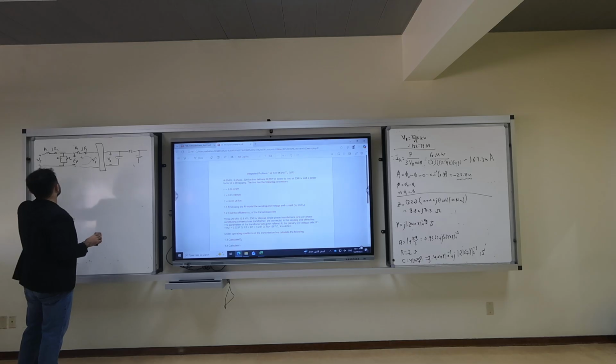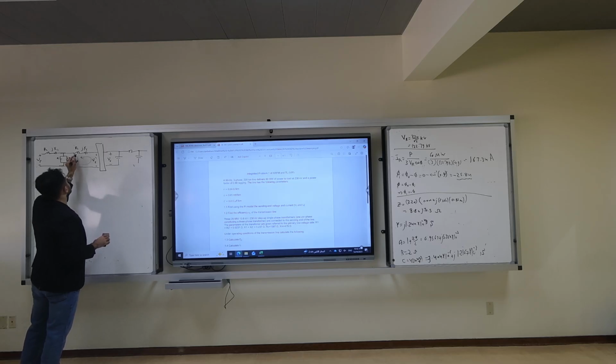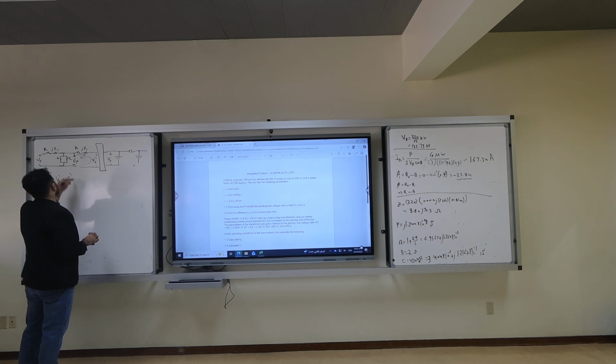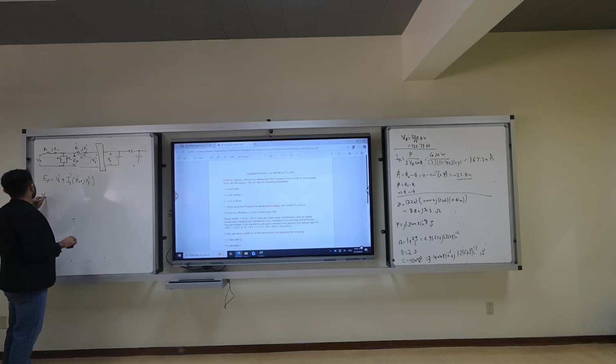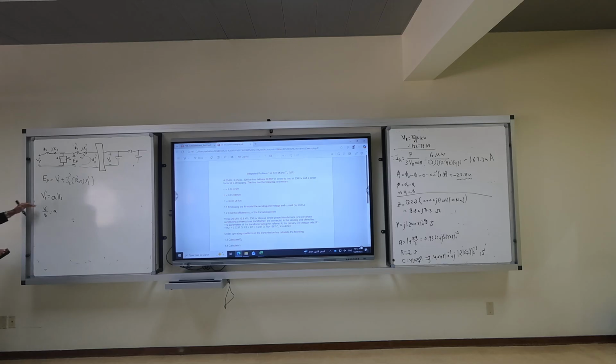So to get EP is VS prime plus I2 prime times R2 plus JX2 prime. You agree with me? So what is VS prime? VS prime is VS over A. No, it's A VS, because VS prime over VS equal A, the ratio of primary and secondary.